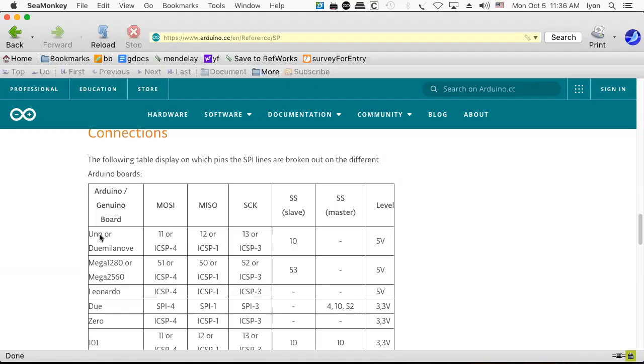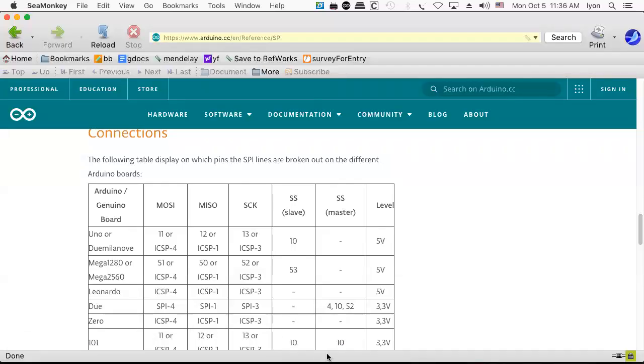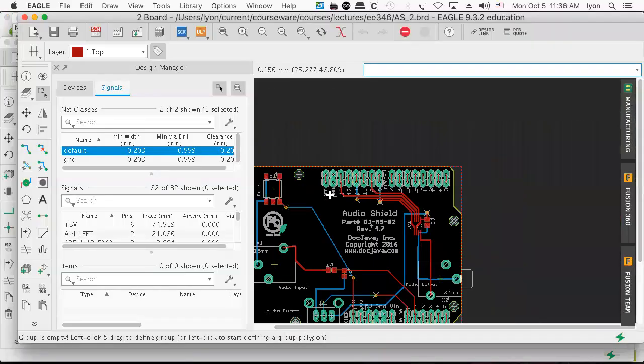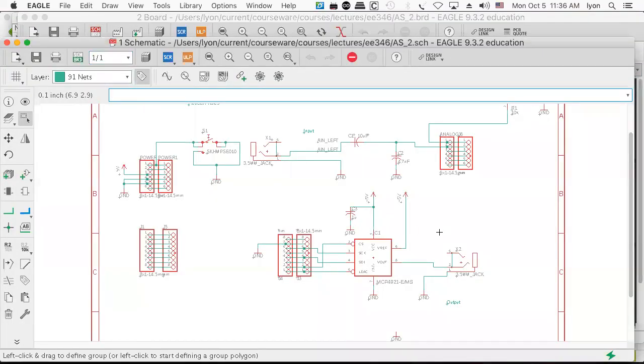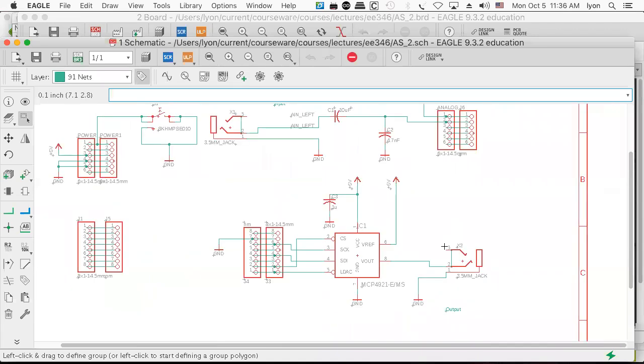So that's cool. And if you go back to Eagle, maybe a little bit more detailed than you like, but it's kind of interesting if you're going to make your own boards. You can click in the upper left corner and switch to the schematic capture. And this maps directly to the board. So as these things change, the board layout will change and you'll have to redo the routing when you go to make your boards.